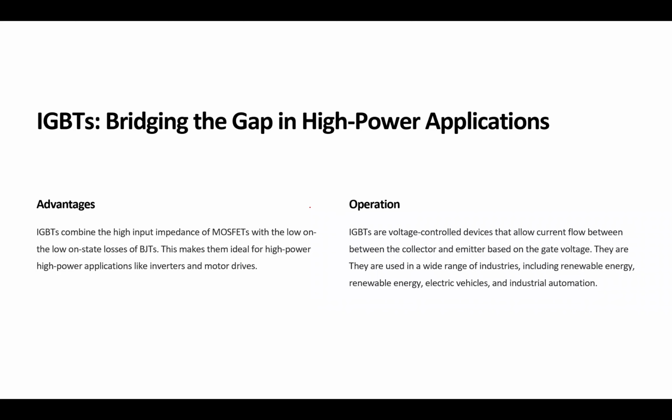The IGBT technology makes those components more efficient. So the IGBT combines the high impedance input of the MOSFET and the low losses of the BJT.